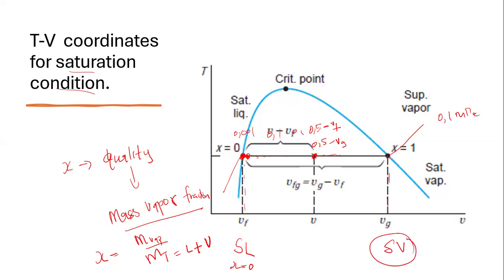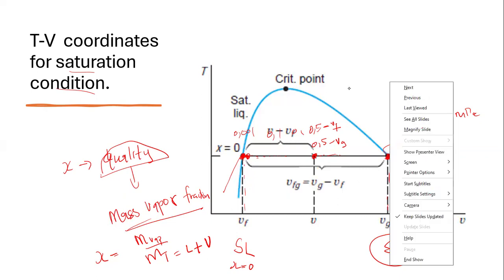Now we can also have the vapor that is mixed with liquid. But when we say X is equal to 1, because this is where gas actually belongs compared to the X, now it is completely describing what the quality is: mass vapor. So meaning X at this point, because it's 1, we have the mass vapor at this point in time.